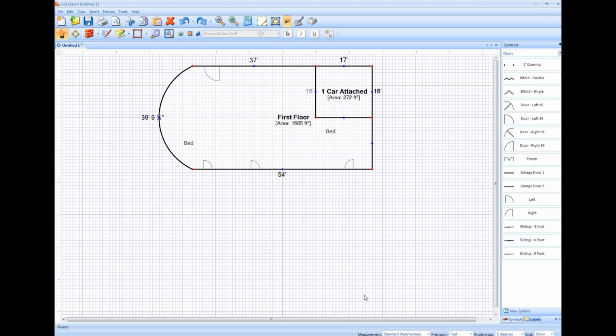So the rise and run method is usually the most popular. That's if you know the depth and the length, or the depth and the breadth of the measurement for that bay window. Let's click into the wall mode and I'll show you what I mean. I'm going to left click to lay my pencil down. I'm going to draw a 10-foot wall to the right. So I type 10, and in the lower left you can see it's been previewed. I'm going to hit the right arrow key on my keyboard and then hit enter to lock it in.